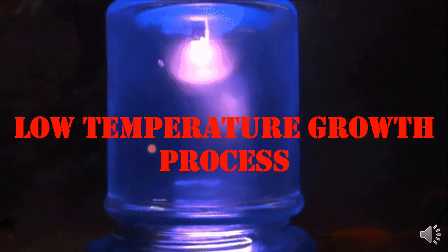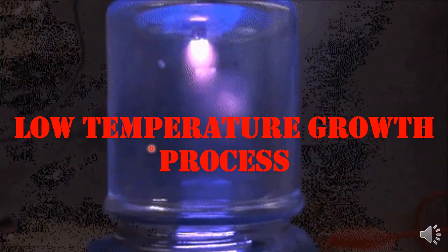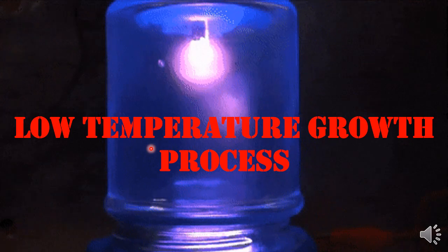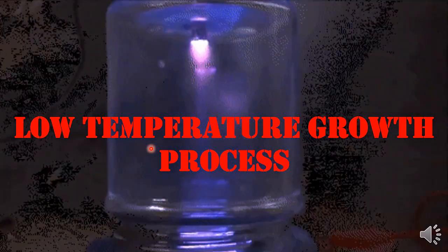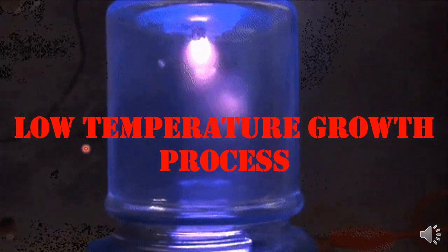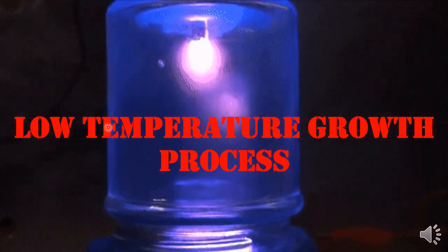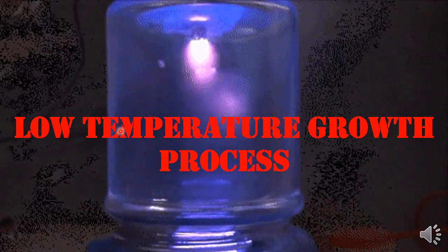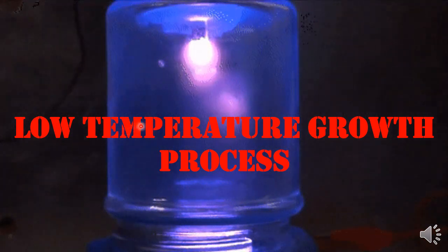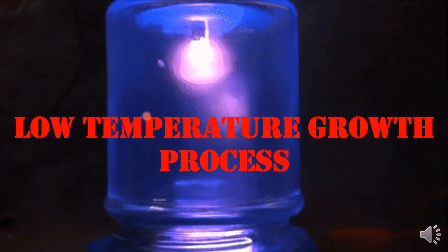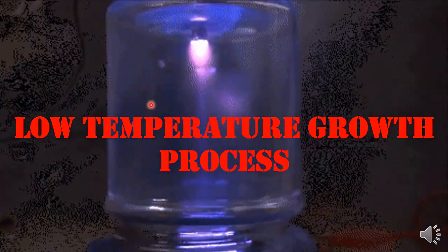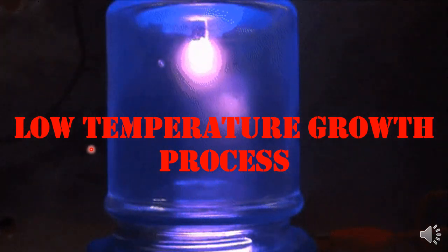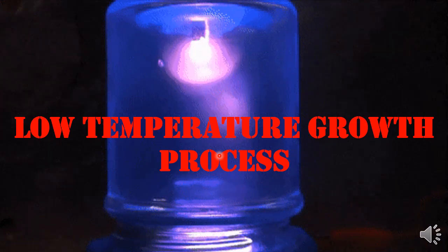Student, please note that the pressure inside the molecular beam epitaxy is ultra high. It is around 10 to the power minus 8 to 10 to the power minus 10 torr. This pressure avoids the collision of the precursor molecules and dopant molecules inside the reaction chamber, and they can easily be transported. Secondly, the substrate which is present is also highly pure and directional. So the pressure plays a vital role in forming the deposited thin film and converting it into a single phase at low temperature.